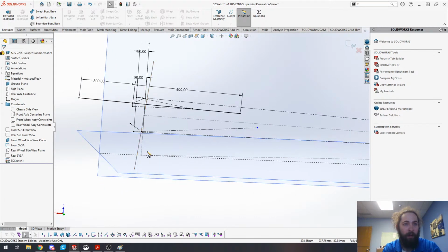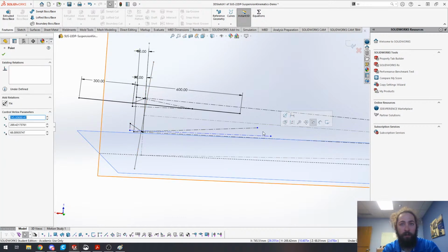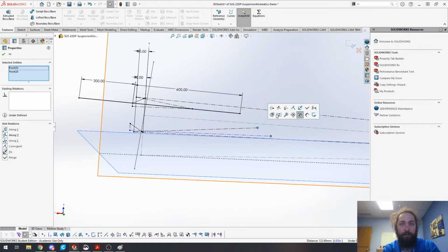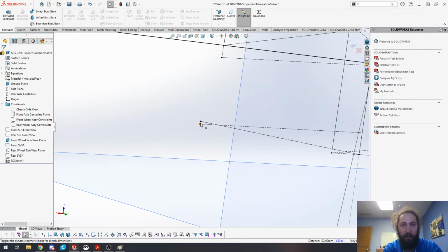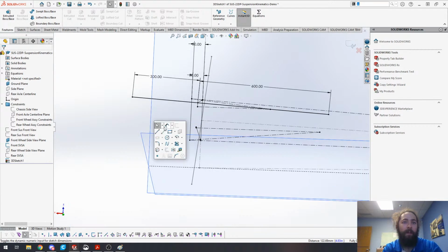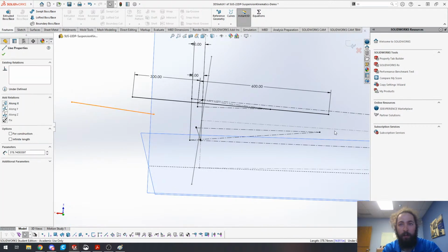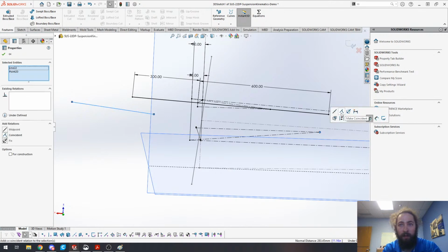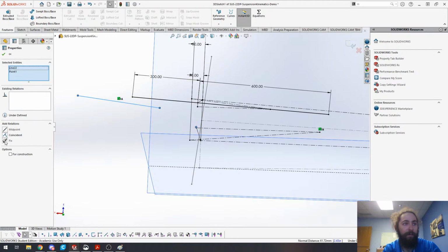And then same thing here. You just have to make a line that's along Z, then along X, and merge these 2 points together. Cool. You can see just how tiny that little discrepancy is along the Z-axis between these 2 points, but you need to make sure that it is there. So we'll make that coincident there, and we'll also make it coincident up here.